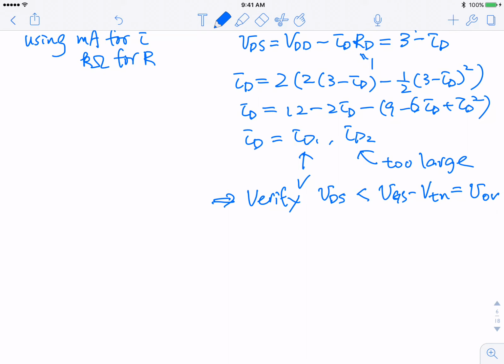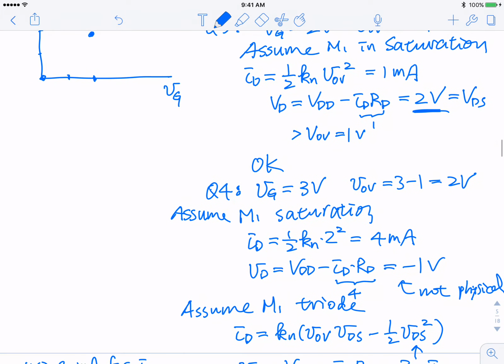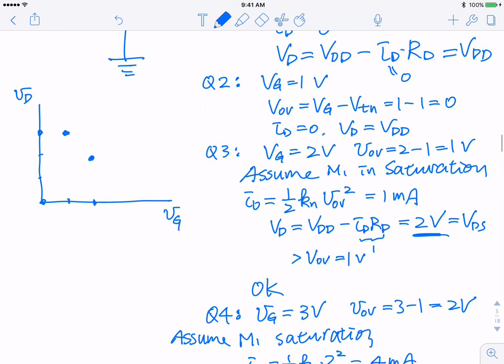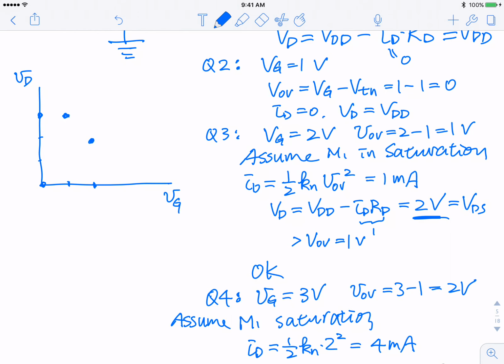You can apply that to many different examples. Okay. One question. For part 3, you drew the graph of VG and VD. Here. Is this graph linear or not? This graph is not linear. So, going to 3, actually I solved it earlier. It drops to 0.7, and then it goes down very slowly. So the transfer curve you get is something like that. So it's not linear.